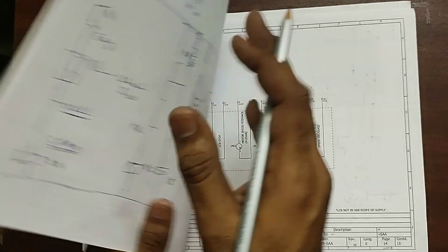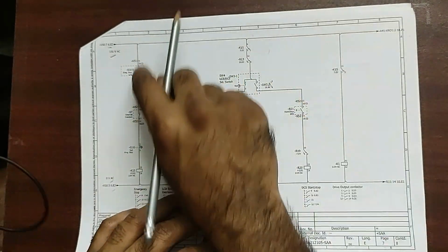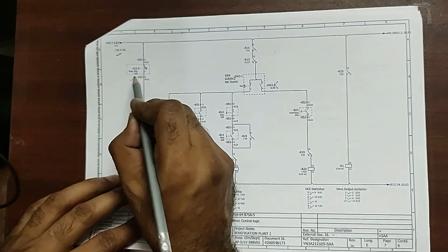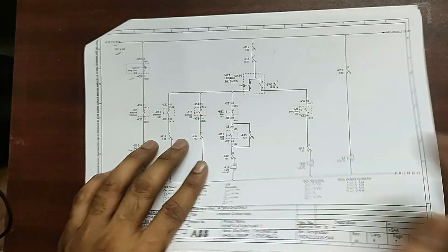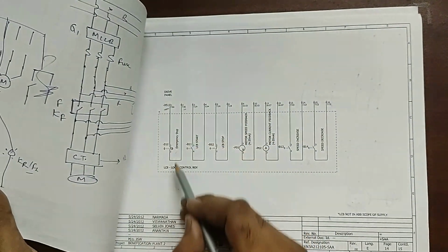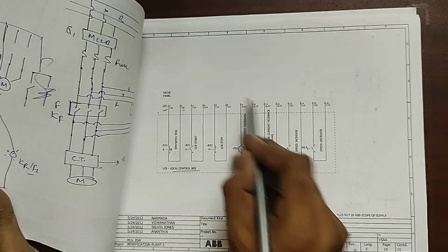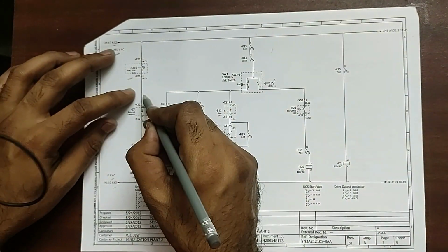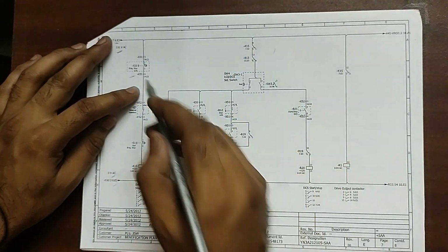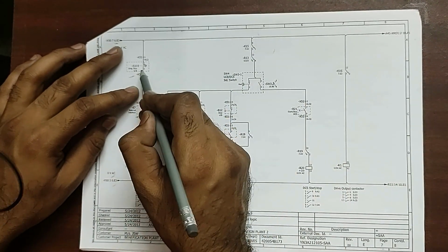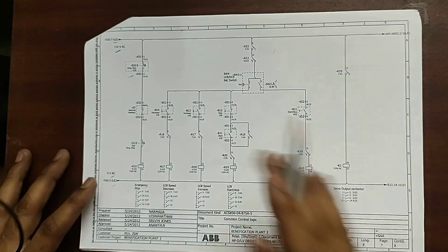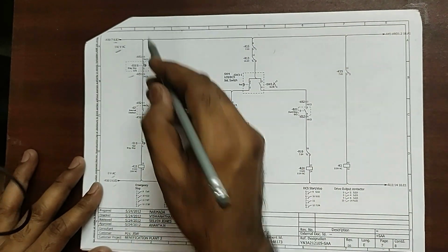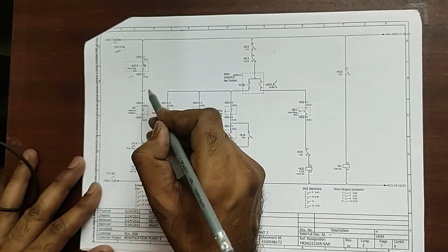7 B2. Page number 7 B and 2. So this is emergency stop LCB. That will go to local supply. See, it is local control board. It will go to the local control board. Okay. So 110, once in the field, if the emergency button is not pressed, it will remain NC because emergencies are kept in NC position, normally closed. So 110 will get here.